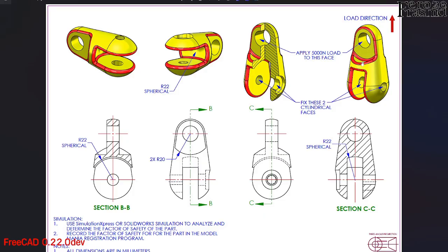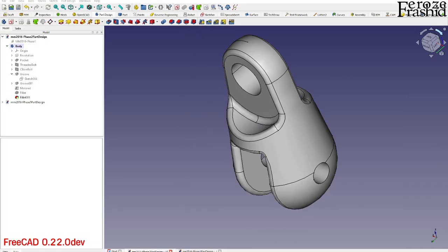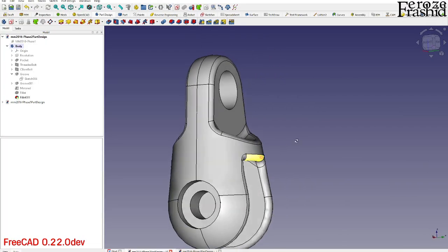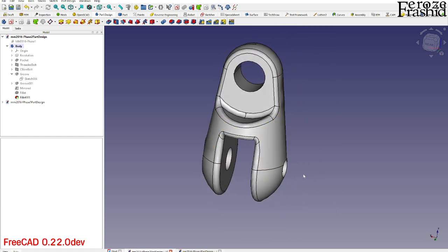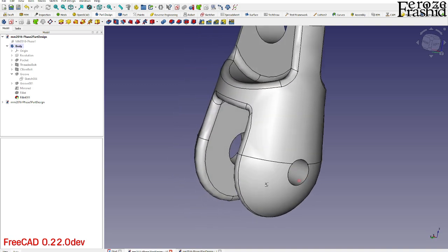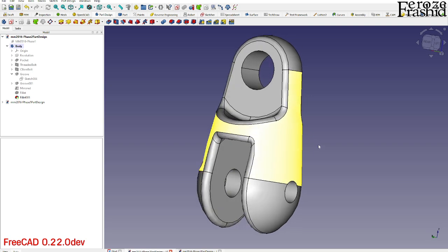So this is what phase 2 looks like. It has these threads, and we established that the threads are there. I just don't want my computer to hang up on me, but the threads are there. And also, now that we did some filleting, I'm afraid to show those threads. That way it may mess up the fillet. If you need the thread showing there, I would recommend you make it visible before doing the filleting, because filleting depends on the edge name. All right, so the modeling part is done.